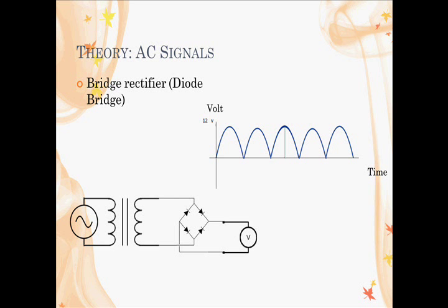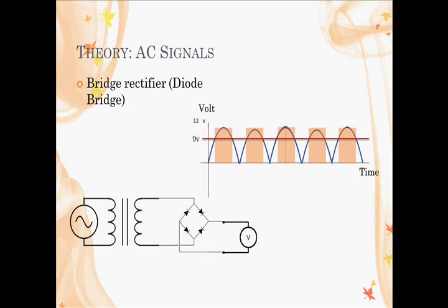This isn't the line we want. This is still moving up and down. And you may say, we have positive voltage, then we can always have that LED. It doesn't matter if it's constant or not. But it sort of does matter. And if you were to look right here, let's say we have a component that only runs on at least 9 volts, and any less it shuts off, and any more it'll be fine, ideally.